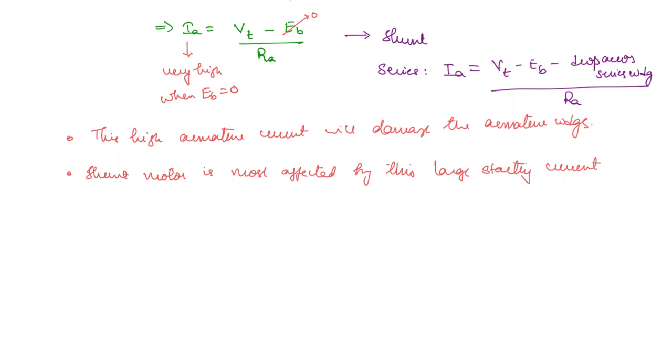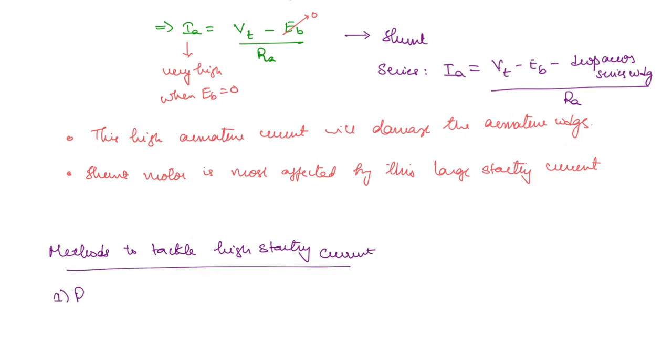And another method, this is one method. Methods to tackle high starting current. First one is reduced voltage during starting.